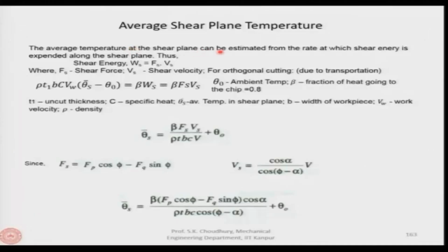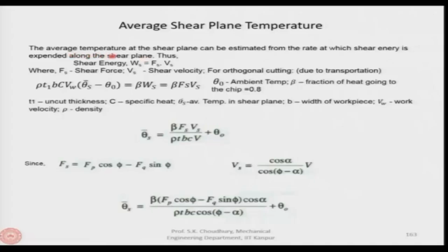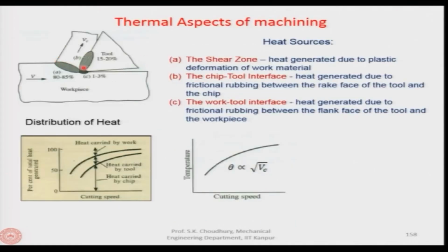Now, the average temperature at the shear plane can be estimated from the rate at which the shear energy is expended along the shear plane. So, we are applying the shear force, we are applying the shear stress, and that shear energy is expended along the shear plane, where the maximum heat is generated. We are trying to find out the heat generated in the shear zone particularly.